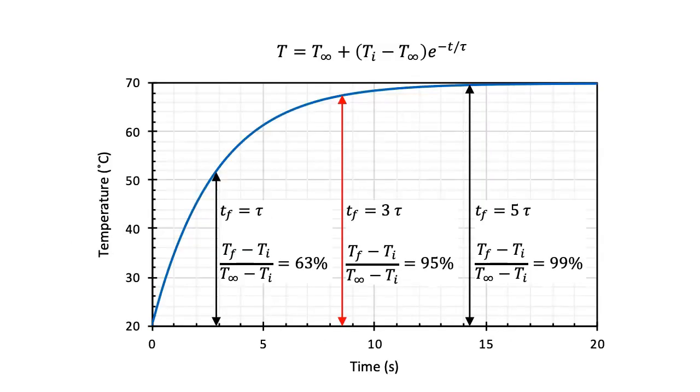To consider these results further, I have used our earlier results to solve for bead temperature as a function of time and used it to make the plot shown. Looking at the figure, we see that the bead temperature asymptotes exponentially toward the fluid temperature with time. Also, note that tau, which has units of time, represents a time constant for the process.